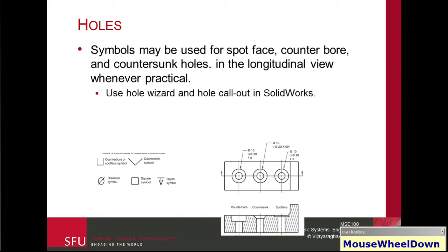When we're using holes, it is recommended that you use the Hole Wizard in SolidWorks, and then it makes our life significantly easier. We're going to do a quick example where we have different features. These are known as counterbores, countersinks, spot faces, and so on. And these are the different symbols. If you're using the SolidWorks Hole Wizard, all of this gets automatically created for you.